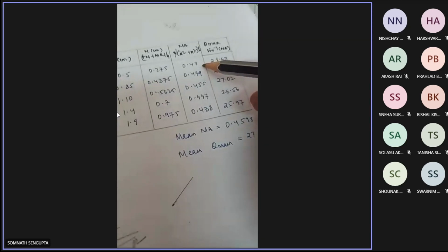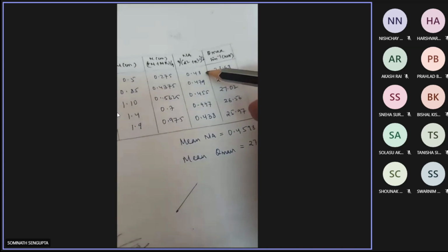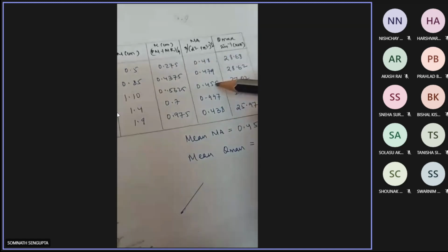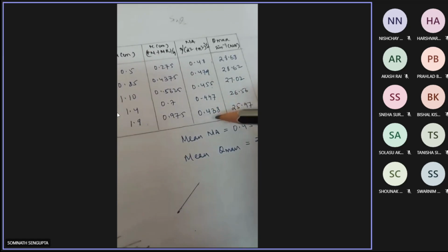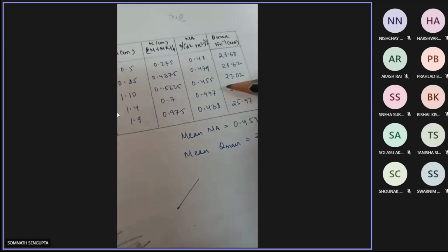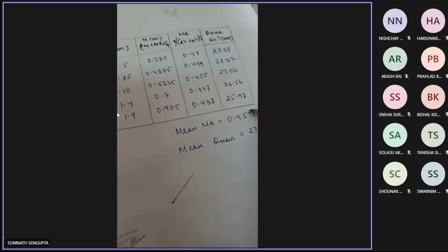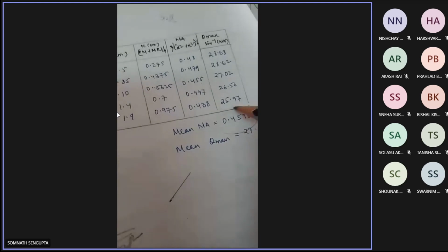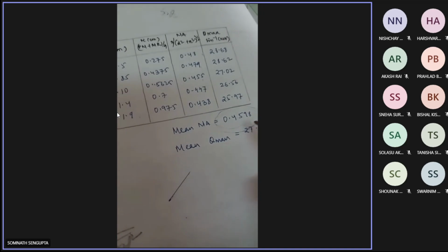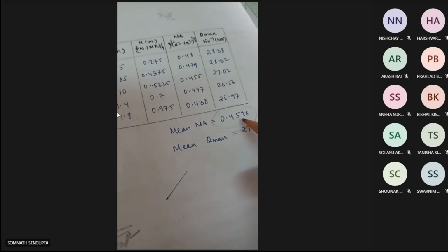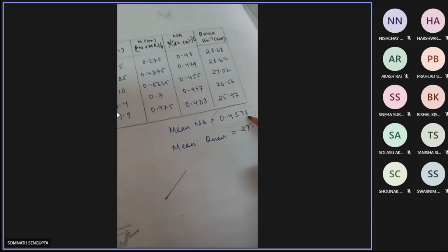So you will see the value of the fiber numerical aperture is coming for the first case, it is 0.48, then 0.479, 0.455, 0.447 and 0.438. Okay, so you have to take an average value of numerical aperture from all these readings. So it is coming to be 0.4598.